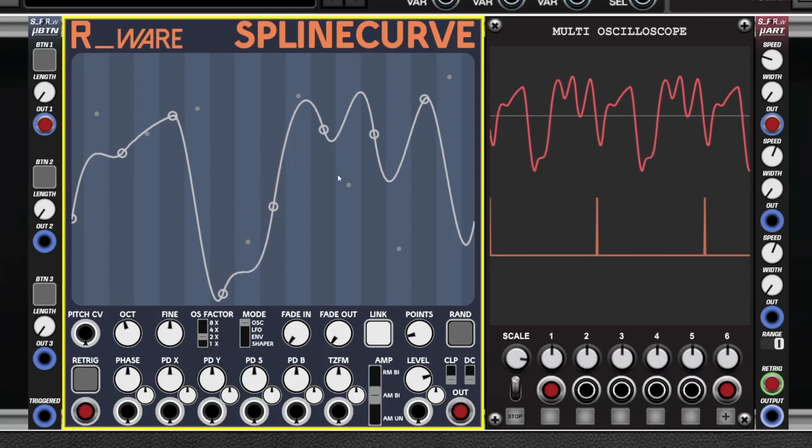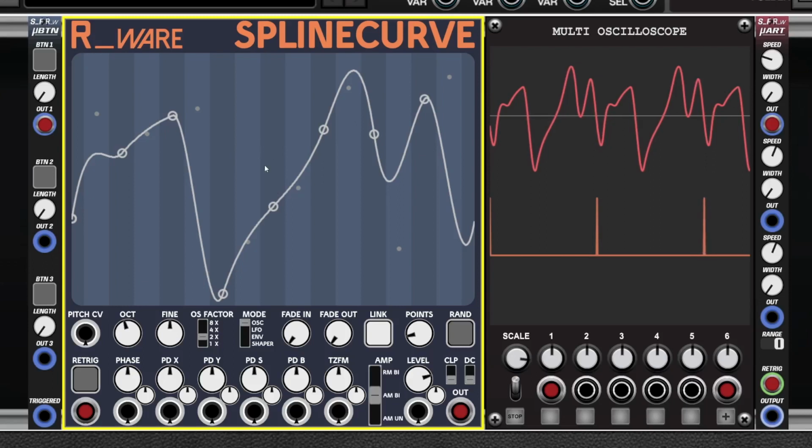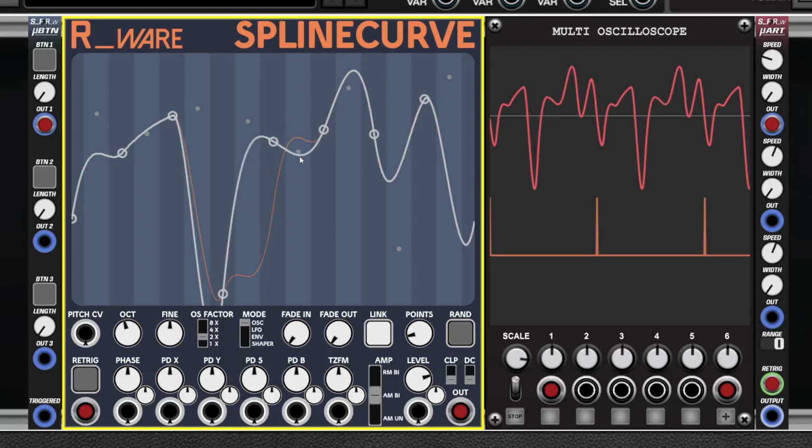The canvas is divided between these two types of nodes. In order to ease manipulating the curve, the canvas is split per node. You can see the stripe pattern in the back. The darker stripes correspond to curve nodes, while the lighter stripes correspond to the control nodes. You can click and drag anywhere within a stripe to place and manipulate the corresponding node. You can also drag the cursor over multiple stripes to influence multiple nodes with one stroke.